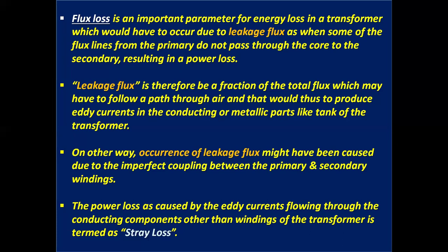Leakage flux is therefore a fraction of the total flux, which follows a path through air, and thus produces eddy currents in the conducting or metallic parts like the tank of the transformer.